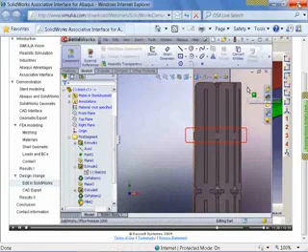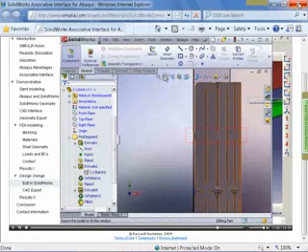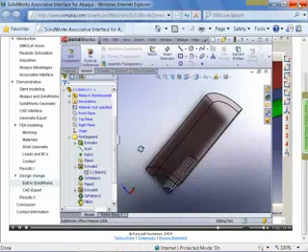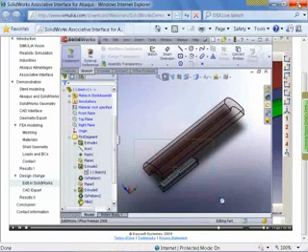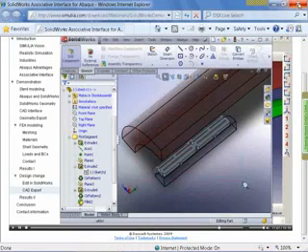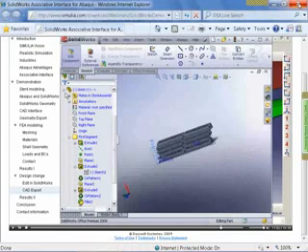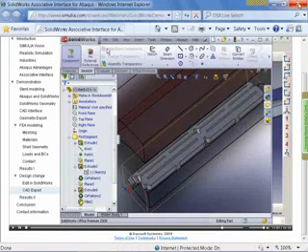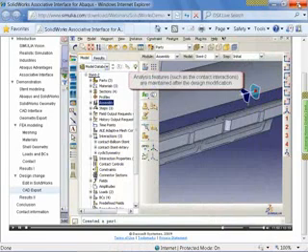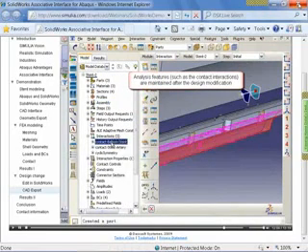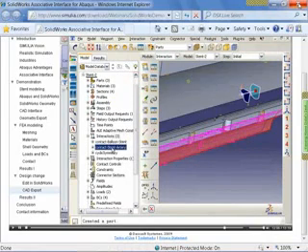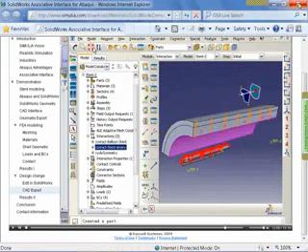Once SolidWorks rebuilds the assembly, we can see that the connections between the loops of the stent are now twice as wide as those of the stent we analyzed originally. Now, I will re-export the assembly into Abaqus. The associative import functionality will update the assembly in Abaqus CAE with the new stent geometry. All the analysis features I defined on the stent are maintained after the design modification.